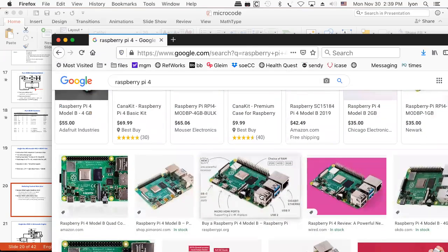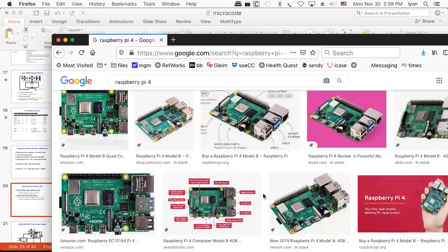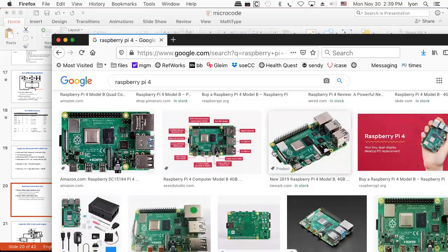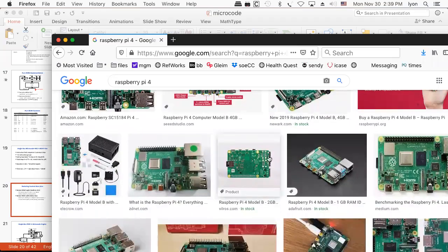But you really don't want it to act as a hard drive server going through USB 2, because that's just way, way slow. And then if you have a camera, you can either plug that into the USB interface, which will be slow, or you can get a Pi Cam. I have one of those, and you can plug it right in here into the CSI interface. That little black area right in here pops up, and you throw the ribbon cable in, and then you push it down. That's how you install the camera. It gives it a very high bandwidth interface to the computer.